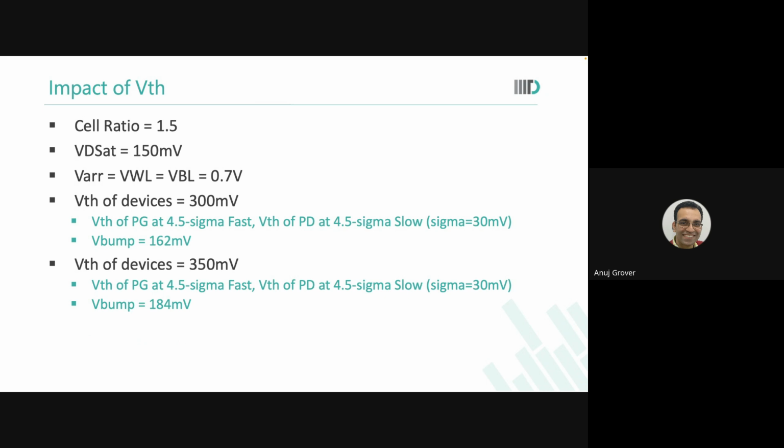What I have not shown in the slides is what happens when you just lower the bit line voltage. Now we lowered the word line voltage, but if you just lower the bit line voltage, what have you done? When you lower the bit line voltage, you have reduced the differential that has to be built across the potential divider. So the Vx will reduce.